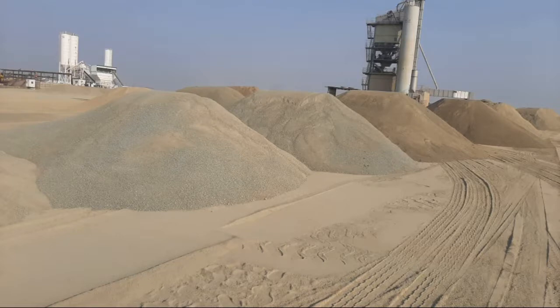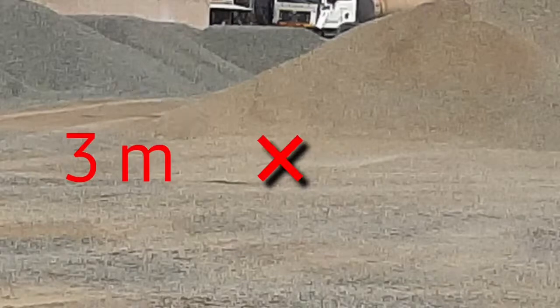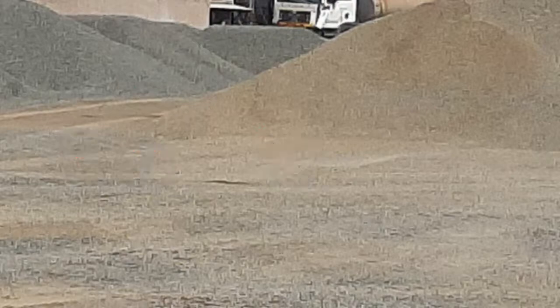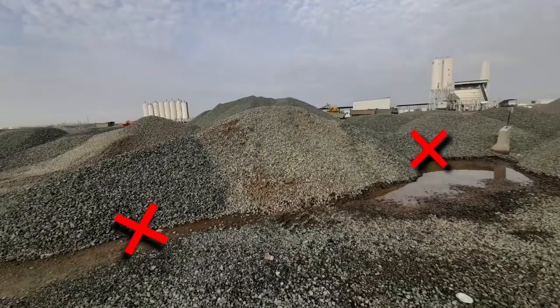All stockpiles should be at a distance of 3 meters so the loader can move easily and aggregate of one stockpile is not mixed to other stockpile. Stockpiles should be free of clay material. Stockpiles should be in dry condition.